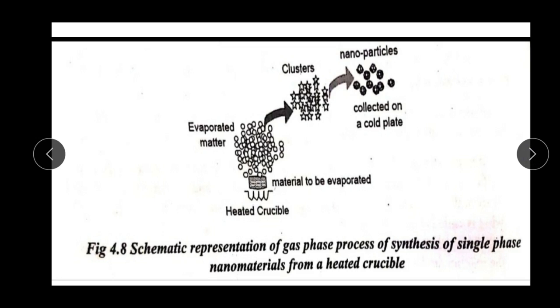Now coming to one more method, that is the gas phase synthesis of nanoparticles. Dear students, gas phase synthesis methods are attracting increasing interest because they offer an elegant way to control the process parameters, in order to produce size-, shape- and chemical-composition-controlled nanostructures.